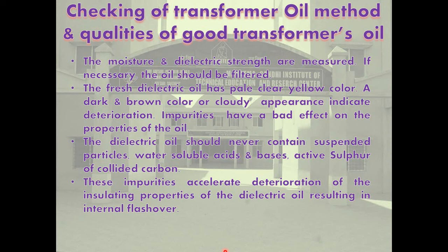Oil in good condition should withstand 45 kV RMS for 1 minute in a standard oil testing cup with 4 mm gap between electrodes. A gap of 2.5 mm should have breakdown value above 45 kV.